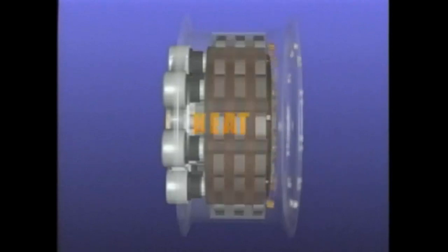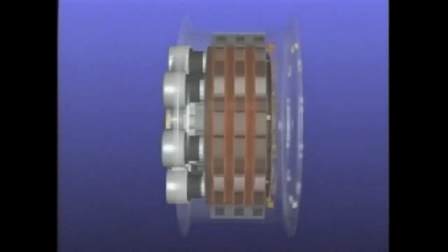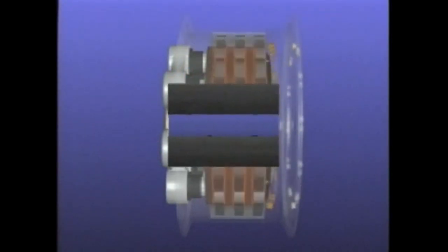Heat is a natural byproduct of braking action and affects carbon brake wear in a rather complex way. To understand the causes of wear in carbon brakes, let's start by taking a close look at what happens between the discs during braking. Every time the disc surfaces rub against each other, carbon material is removed. At first, large particles wear off and remain in the interface between the two discs. These act like an abrasive sandpaper affecting both surfaces.